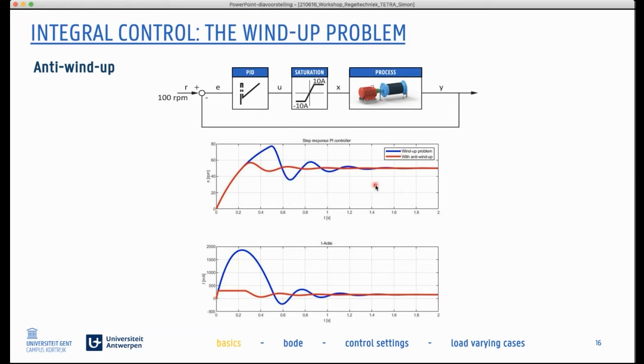If you have any software where you have an option to have the anti-windup cancelled out or the anti-windup active, always put on the anti-windup. Always. There's no reason why you wouldn't select the anti-windup option unless you want to educate students and you want to show the effect of an integrator which is not limited, but always limited.